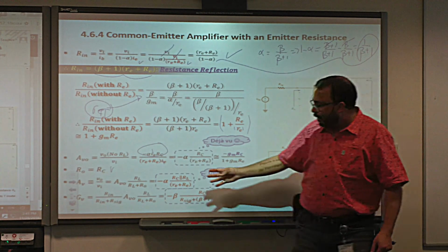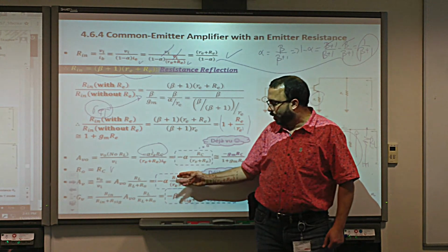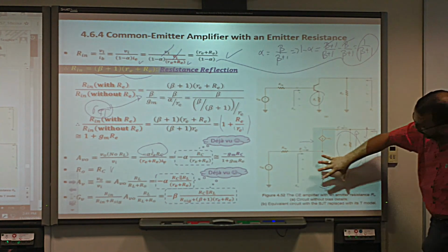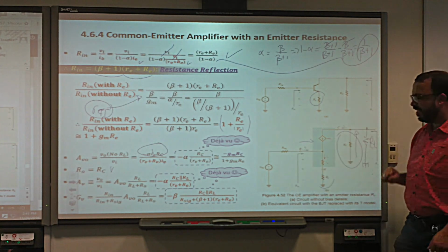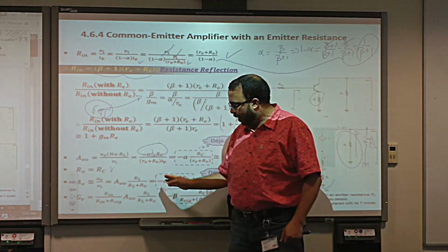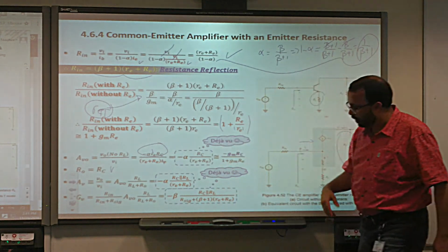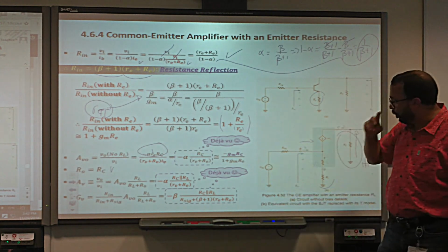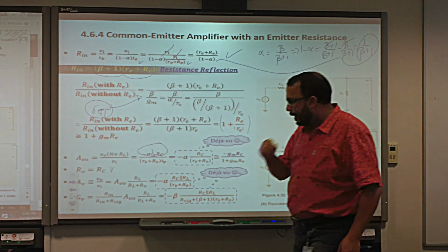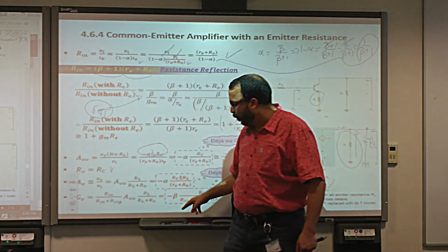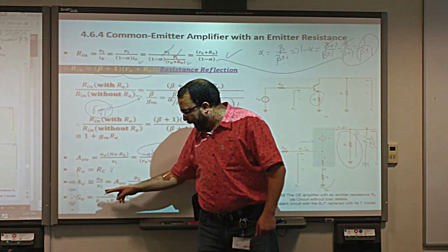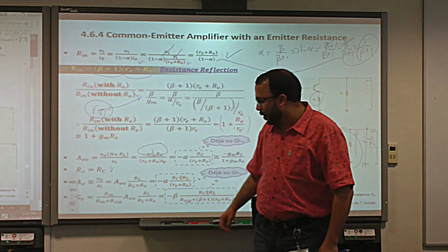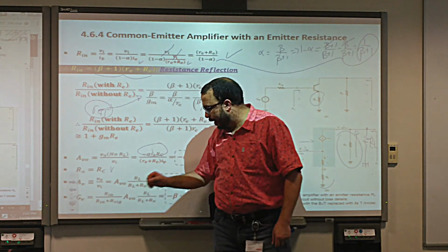And again, the same story: the total collector resistance, these two in parallel, divided by the emitter resistance, which is this one in series, of course with minus alpha. Alpha is almost equal to 1, so it's not a big deal. Now for the overall voltage gain, we apply the whole formula: the voltage divider at the input and the output, times the open circuit voltage gain, AV naught.